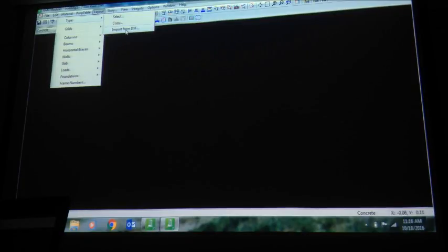Okay, so any CAD drawings, which is a DWG, right? CAD drawings and DGN for MicroStation, or I'm not sure about the Revit, RVT. Any of those environments, you can save those files as a DXF file, and once you have a DXF file, you can import that DXF file. It will come out in a RAM format. So that's the easy way. Nowadays, all the structural software is linked with Revit or CAD. You can import it and you can export it. So you do not have to redo it.